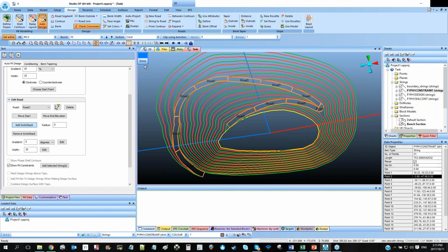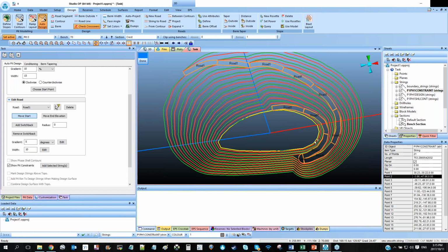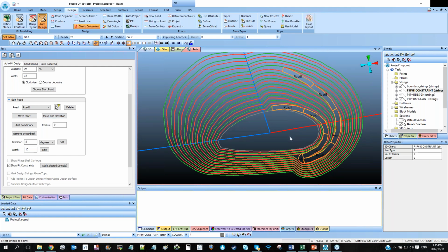All right. You can obviously still move the starting position of a ramp, and the switchback remains on that specific elevation that you defined. And you can define also the end elevation of the road to stop on a given contour, if you will. Okay. So this gives you, in a nutshell, an idea of what the tools that we have put together can do, and then I'll try to now show some application of those tools on a real pit data set.